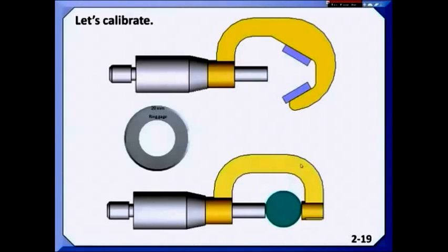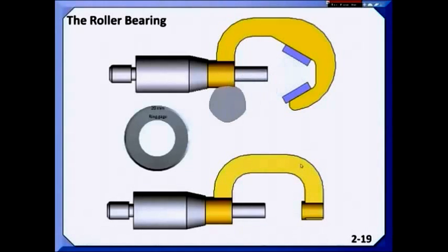and our 2-point micrometer. We then bring in that 5-lobe part, which is very common in centerless grinding, 5 and 7-lobe parts, even 3. And we show how, no matter how you mic that bearing, you could not detect the lobing effect. And even if you put it in the anvil mic or tri-mic, as you rotate it, the mic would not change. But if they had followed Rule 1 and checked the perfect form at the maximum material condition, they would have found that that had a lobing problem.